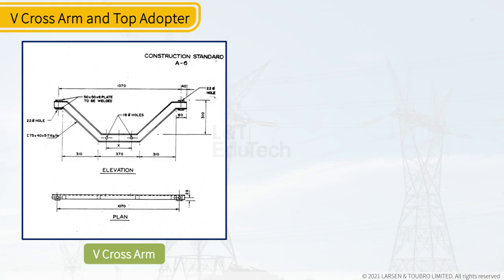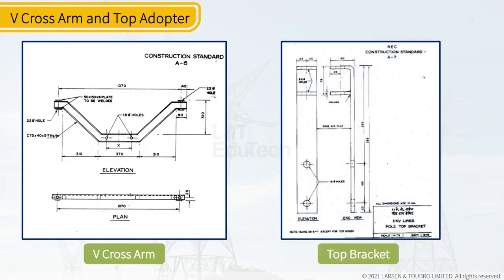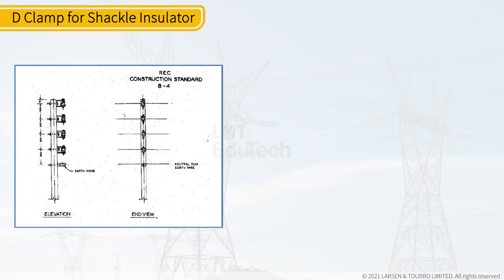The pin center to pin center distance shown as 1070 mm is in line with the clearance required between the faces. When the top bracket is introduced and the pin is fixed to it, we will get a triangle. If we measure the clearance between the three pins, we will understand that the clearance available between the faces is approximately 535 mm.